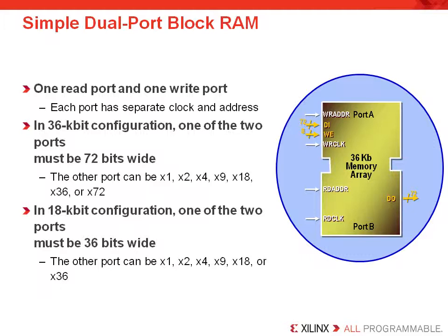Now parity bits can be used for parity generation, which is left to the user to encode into the initialization of the memory. But effectively, the extra bit width can be used for anything, since it's being stored in memory like any other bit. Now that's why each block is 18K bits, not 16K bits. So while there is no built-in parity checking logic, the extra space for you to store that bit has been allocated in the block memory's construction. However, you will still need extra logic to check that your data is accurate for the parity bit.